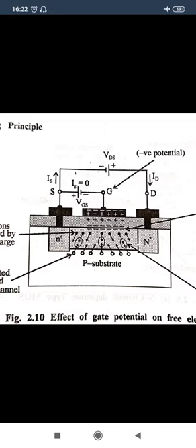So recombination processes occur, and the conductivity of the channel depends on these carriers. According to that, when we apply the negative voltage to the gate terminal, it depletes the electrons from the channel and attracts the holes from the P-type substrate towards the channel.